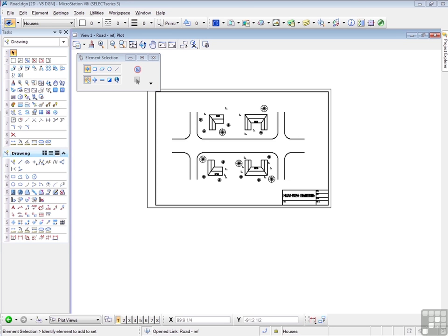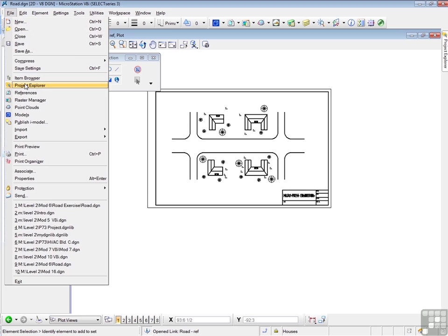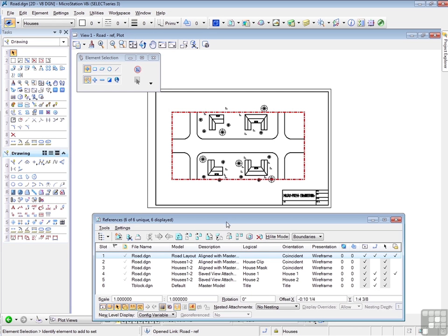You will also look closely at models in MicroStation, where information can be separated into discrete subfiles within a design file. You will work with the simple design shown on the screen to fully understand the application of references and models. Let me show you what I mean. Here we see the end result of this exercise, and building up to it, you will create a series of subdrawings and save views, which will all be referenced to a sheet model ready for plotting.